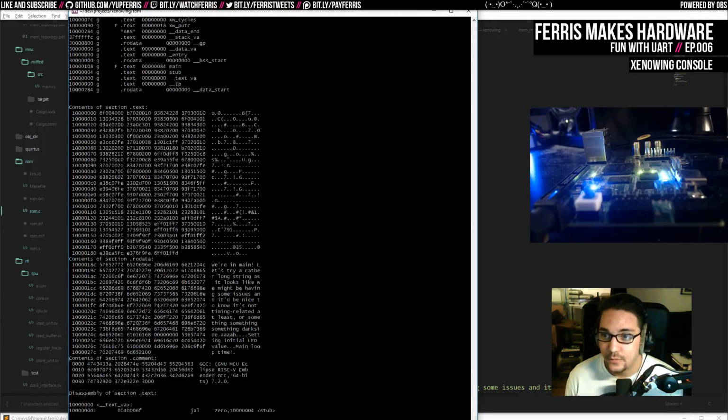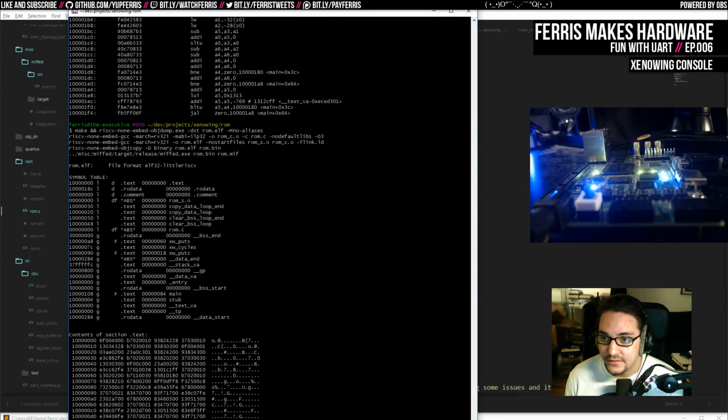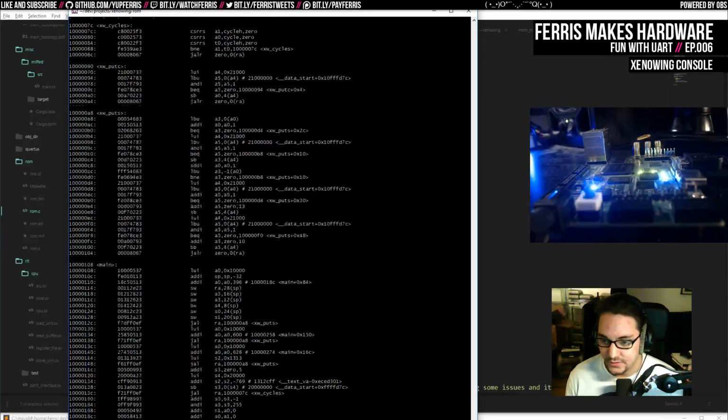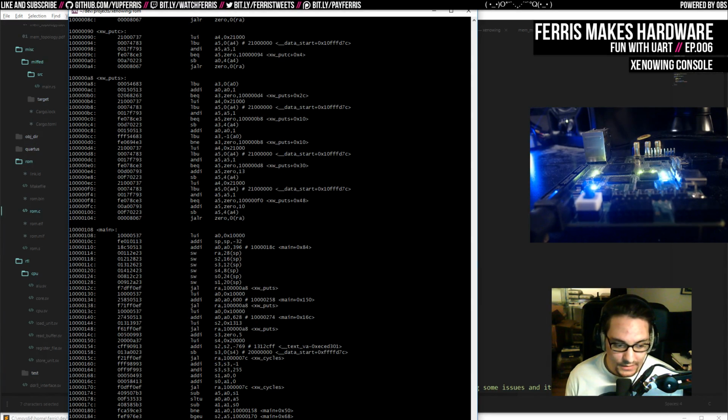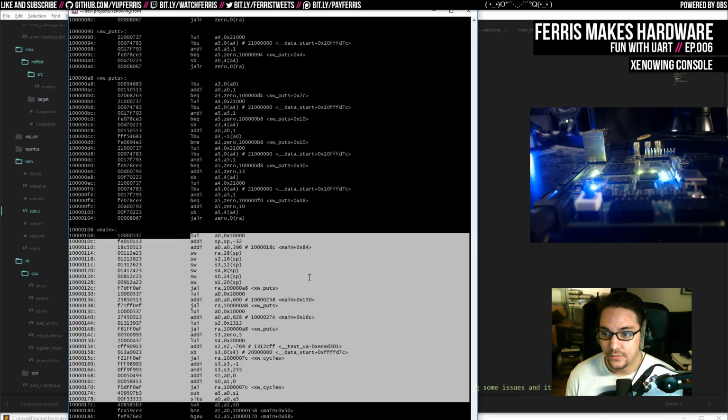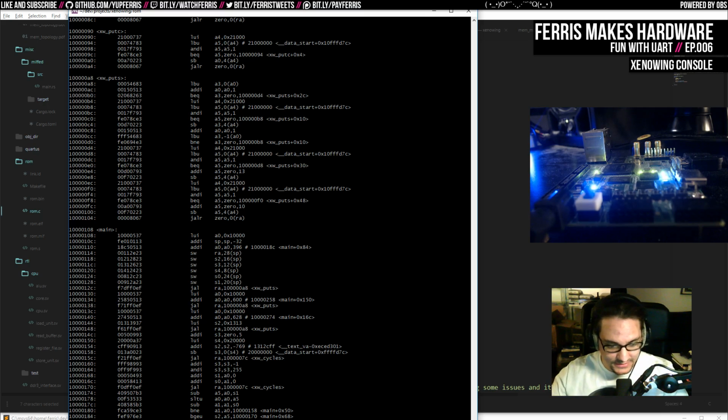And the code here is also really easy to read. I also have this dumping with this dash. Where is it here? I'm not seeing it. Here. I'm dumping this stuff from the elf file, which is sort of an intermediate when it's making the ROM. And I have this -M no-aliases, which means all those pseudo instructions from the RISC-V specification, this strips all those. So this will actually give me the exact instructions that it's running, which is a lot more helpful when you're implementing the CPU, because you can see the exact instructions that are running rather than their aliases. So that's really helpful.